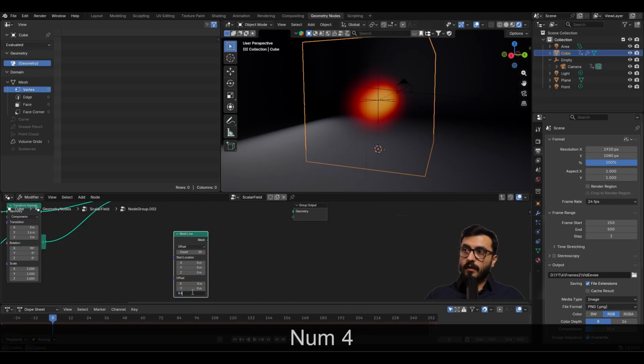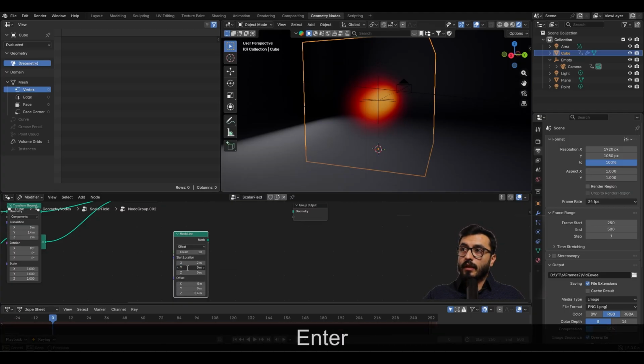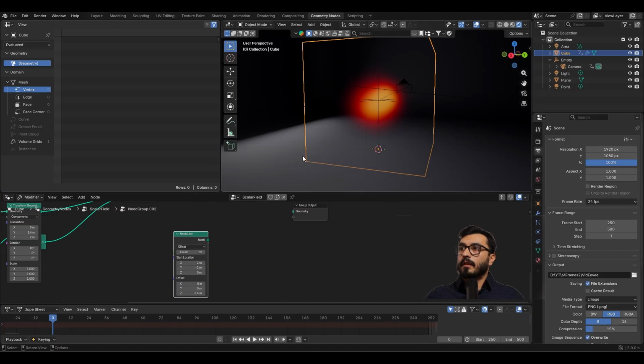So this will be the step of the points that we will have, and we will start with -2 in x, -2 in y, which will be this axis here. We will start 0 in z, so we will do 1 point each 0.4 or 40 centimeters. Just remind that this is 4 meters height, so this will cover the 4 meters.